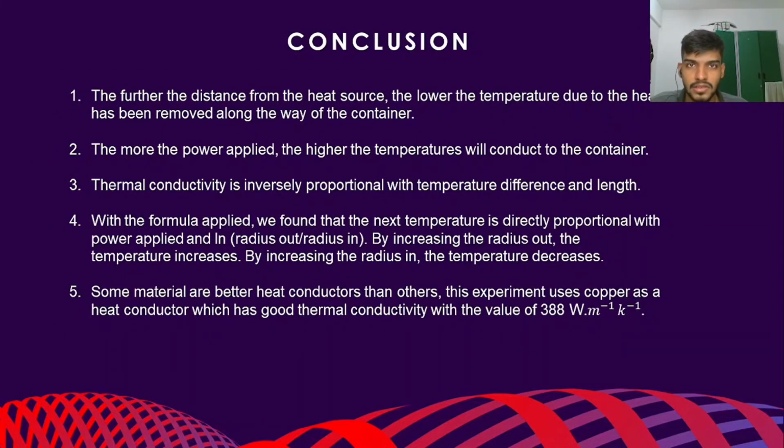And lastly is the conclusion. There are 5 points. First, the further the distance from the heat source, the lower the temperature, because the heat has been removed along the way of the container. Second, the more power applied, the higher the temperature will conduct to the container. Third, thermal conductivity is inversely proportional to the temperature difference and length.